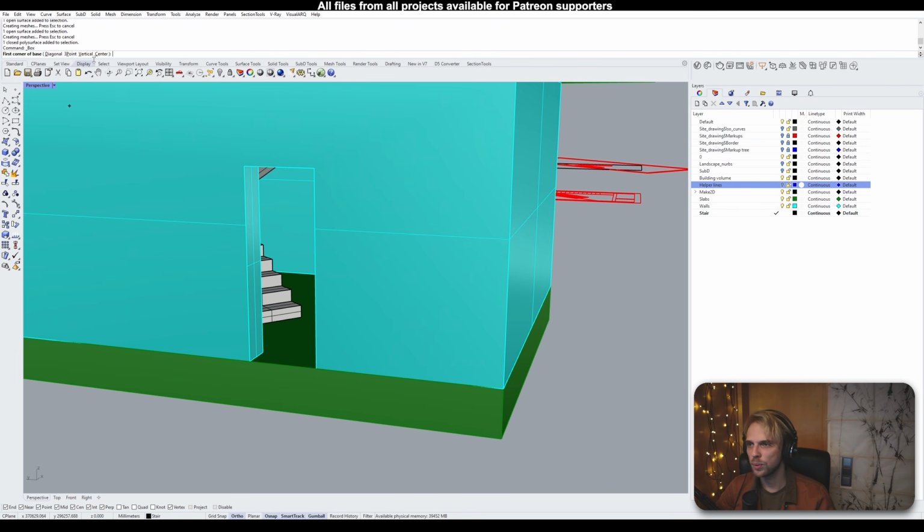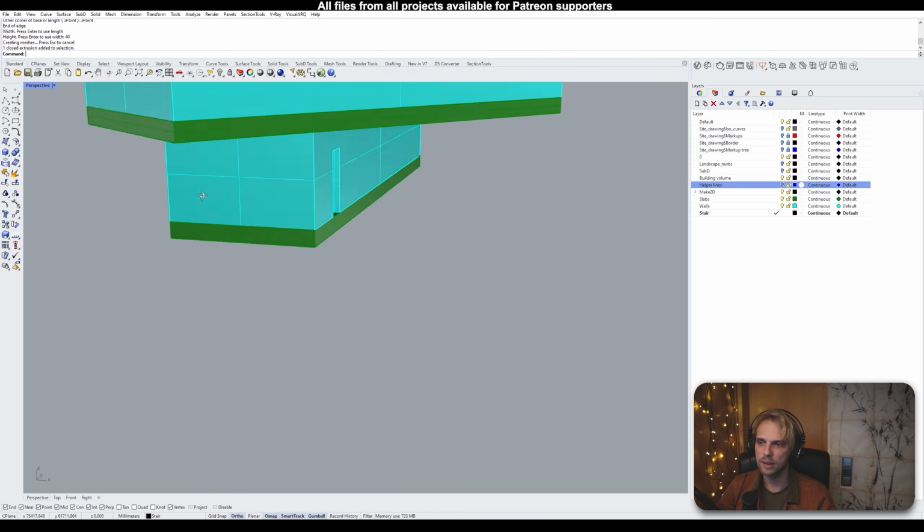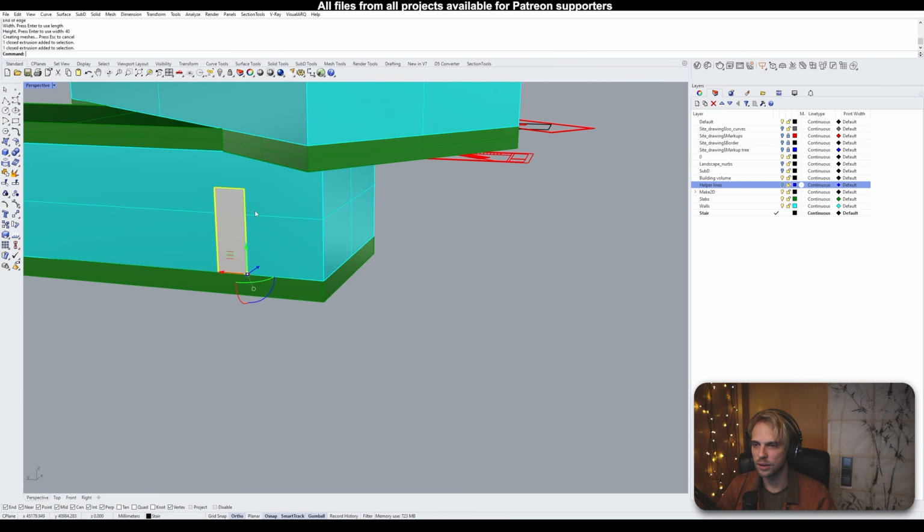I would suggest while you're just sketching, keeping them, you know, as holes. But if you just want to see like the facade enclosed, then just make a box. 3-point box works the best. And for the door, we just use 40 millimeters, right? Push them in a little bit, like 20 millimeters in to get that little lip. And that's it. That's enough to get the doors.